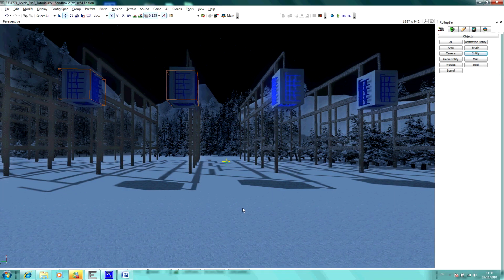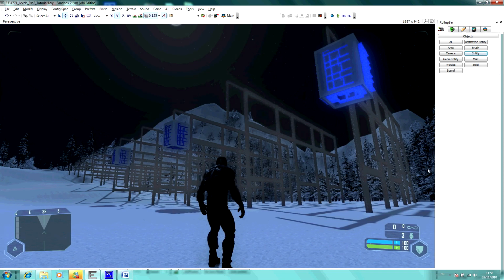So you can see how you can copy your object multiple times to create multiple lights that will trigger on when you enter the trigger area. The only important thing is to remember that your flow graph must be attached to the objects that you wish to copy. I hope you have found this tutorial useful, and you can now find other ways to create interesting lighting effects. Thank you.